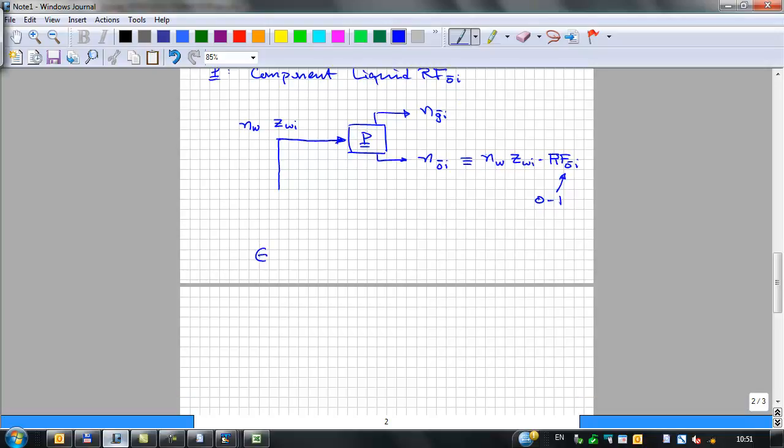Okay, so the gas-oil ratio will be the moles of gas, right? Pound moles, let's say, times 379, right? That's standard cubic feet per pound mole. Divided by the moles of oil times the molecular weight of that oil divided by its density, right?